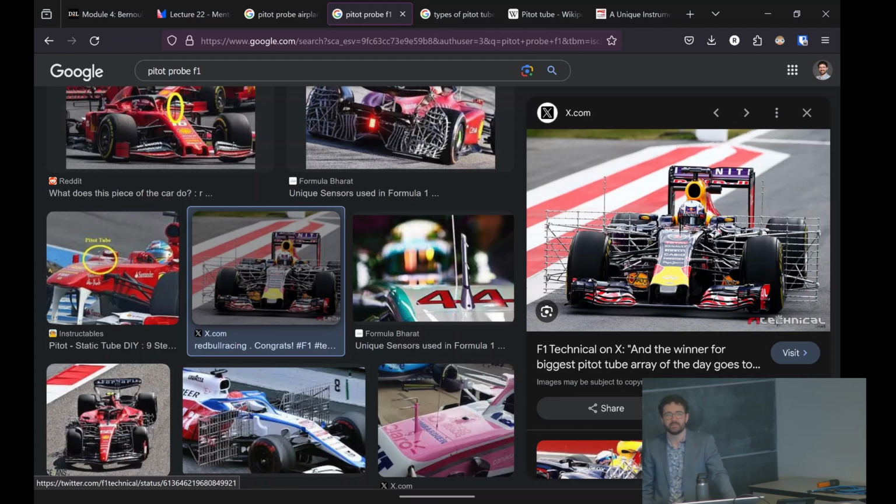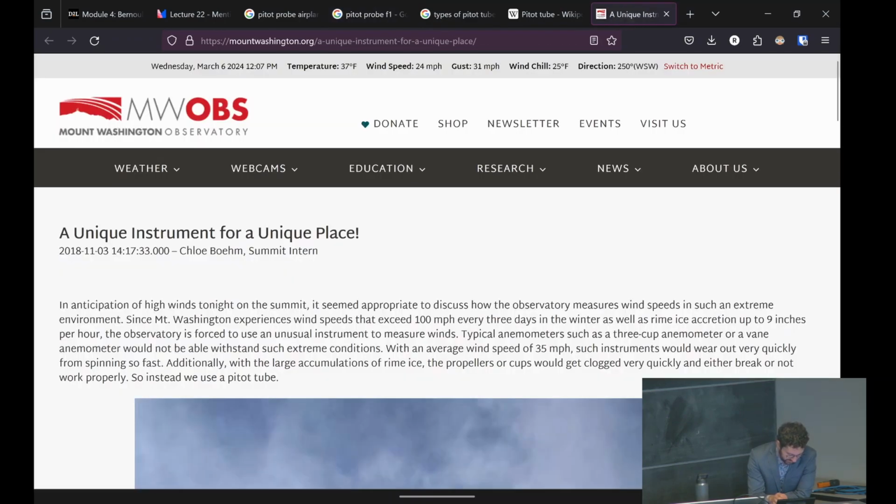Exactly. So if you stick it right at the front, it hasn't really recovered, and you might get very small vortex shedding near the front of it. So that's the reason, it's a very good observation. The static probes, the static holes, are usually a little bit further back, so you get nice flow over them. Any other questions?